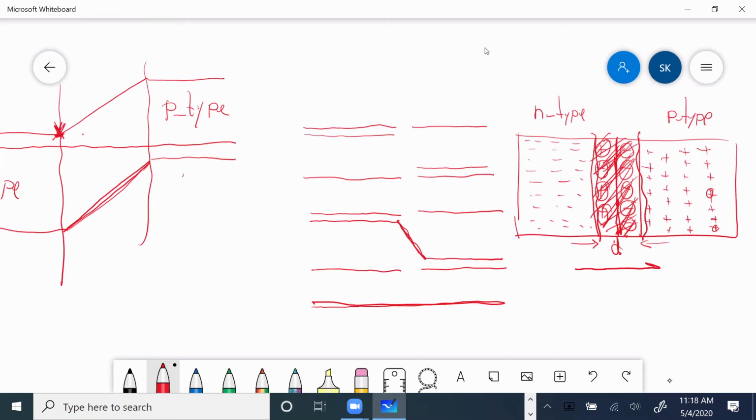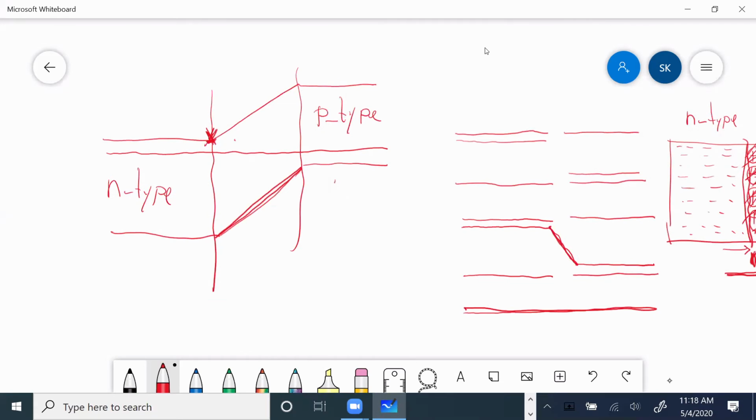I want to know what happens with the Fermi level as I travel from there to there. I want to know what happens at that region. So I'm starting from here. My Fermi level is still N-type. The material is N-type. Then when I enter the depletion region, it starts with N-type. Then it becomes less and less N-type.